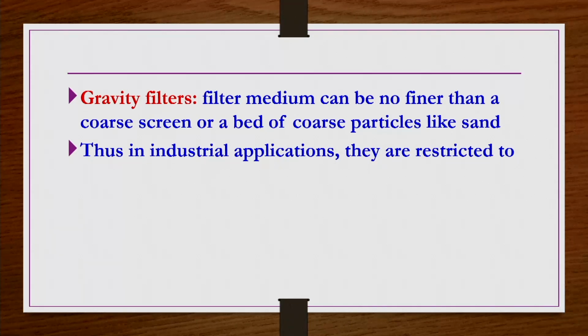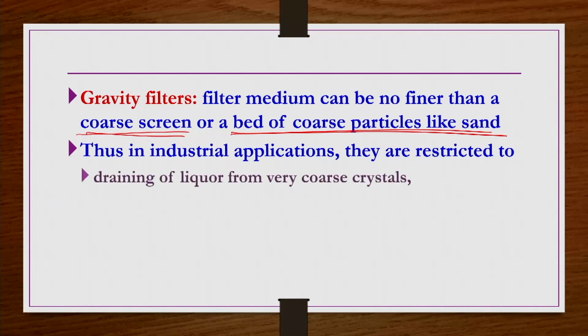Because the filter medium is just a bed of coarse particles like sand, which can retain only the coarse particles present in the solution. So industrial applications are restricted in general to draining of liquor from very coarse crystals, clarification of potable water, or treatment of wastewater, etc.